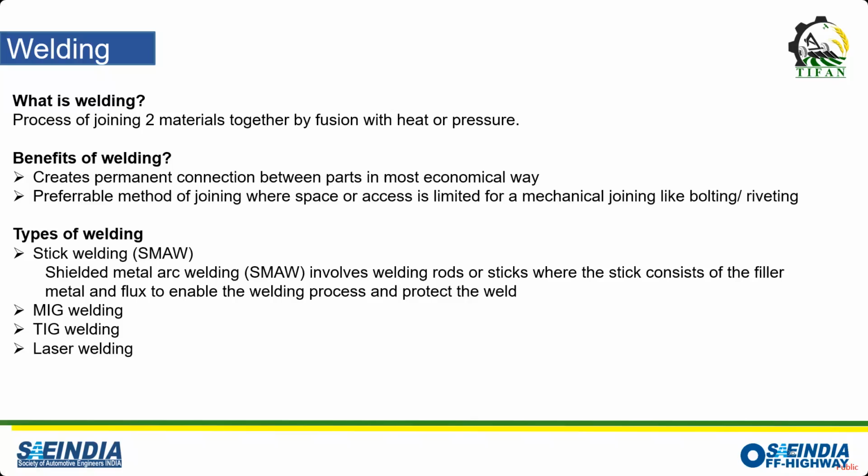In the case of serviceable joints, when we want to change the components and the parts need to be removed a couple of times, you have to choose the bolted design because that is easy to unclamp and clamp again. But when we talk about permanent connections, welding is the most economical process, and it creates permanent connections which have good strength, as good as the strength of the base material.